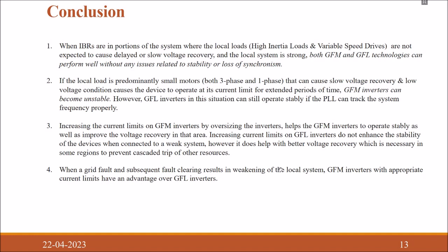And the last point would be that GFM inverters are more appropriate to install in weaker grids, and when you have a system which has local loads of variable inertia, it is better to have a grid forming inverter in a weak grid than using a grid following.